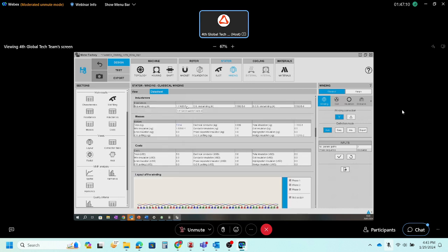Okay, this value is quite useful when you need to perform some analysis with the finite element model, like Flux, because normally this value has to be computed manually by the user. So it's something that you have to add in the circuit, but it's not a known value, a very known value. You have to compute it considering the end winding geometries.